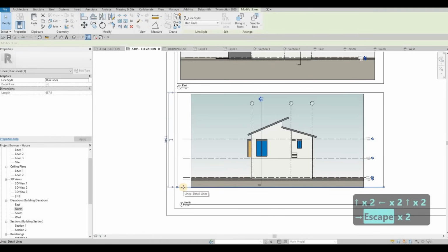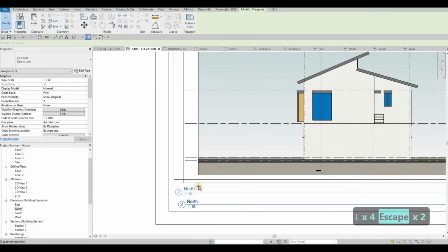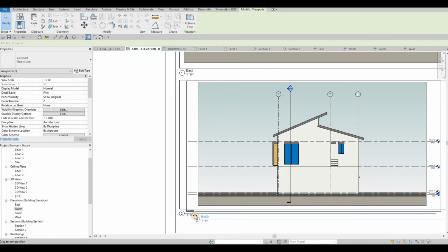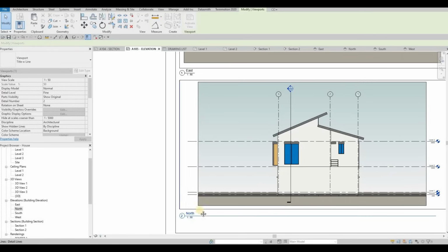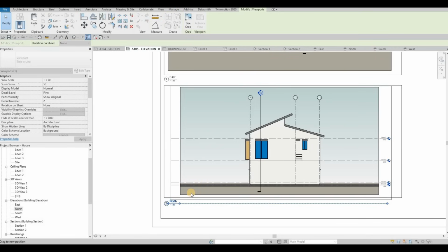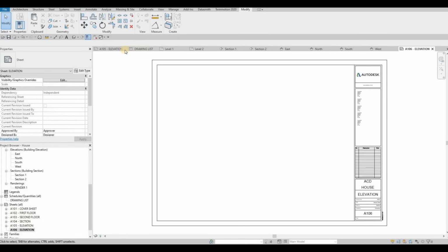If you need more space, you can always drag this one down, select this, always show this one so that everything will align. As you can see, there's imaginary line or temporary dash lines, and then clean it up. And then go to the last elevation.